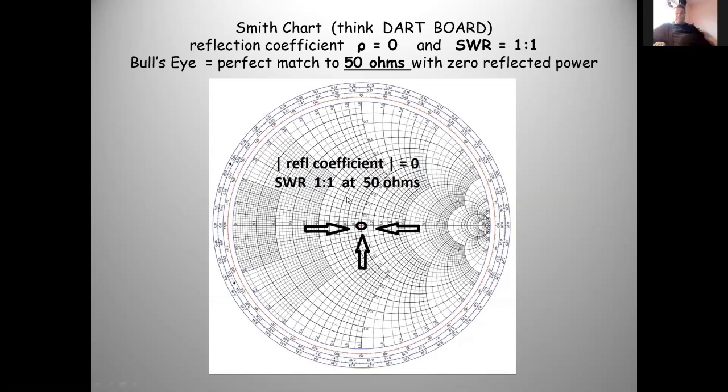Okay, thank you. So what if I plug this into my coax and at the other end I have a 50 ohm load? Maybe it's a dummy load. Maybe it's my antenna. But it plots right here at one frequency. Oh, that's really cool. I can't get better than that. My antenna plots right at the bullseye. The reflection coefficient is 0. My little NanoVNA is not getting anything back, so it infers something from that.